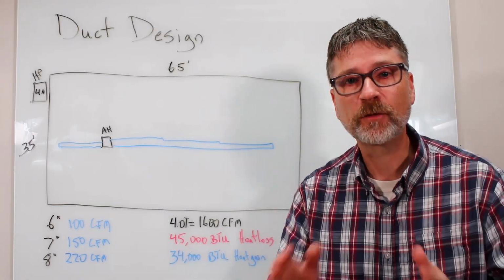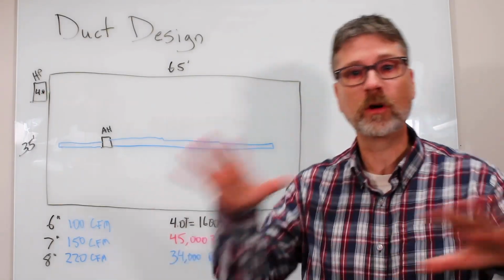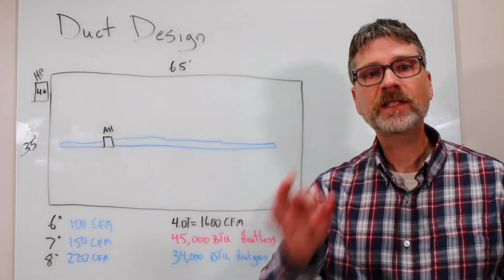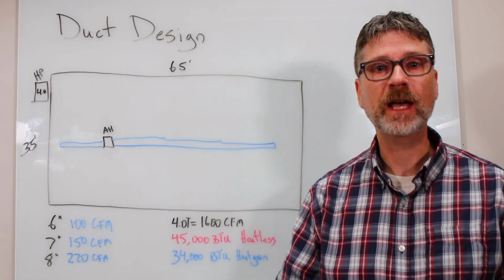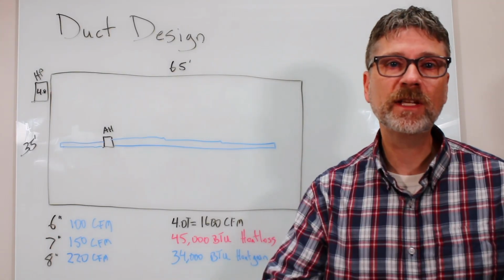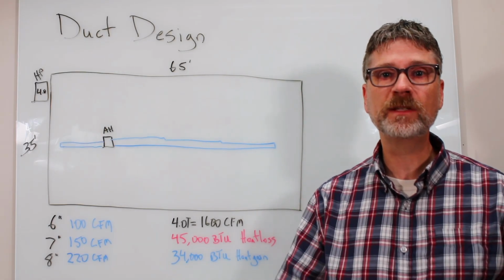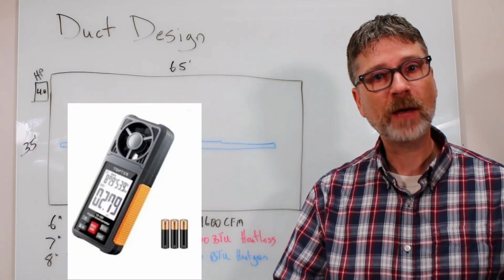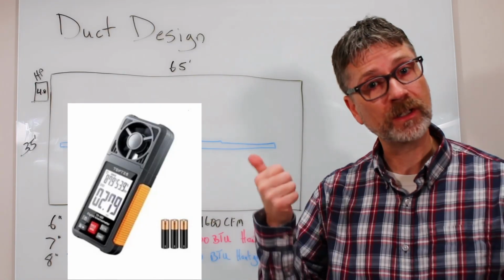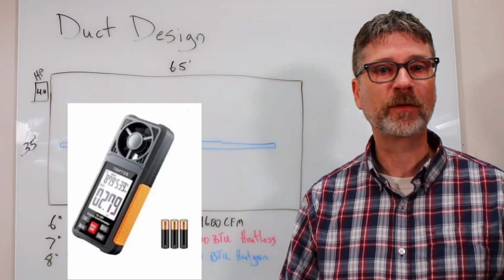And of course, different climates demand more of one than the other, more heat or more cooling, depending on where you're living. So instead, let's talk velocity, or FPM, as the one that's easy to understand and converts quickly to CFM, or volume. You can measure FPM, feet per minute, with a simple handheld anemometer, and you can get those for only about 30 bucks on Amazon. Here's an example of one right here. That's the $30 one that I would use from Amazon.